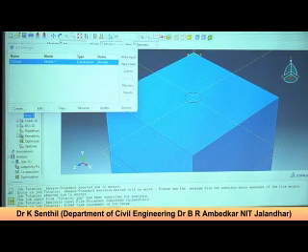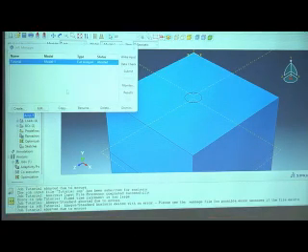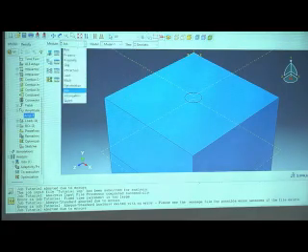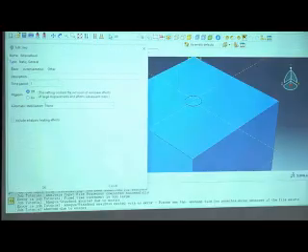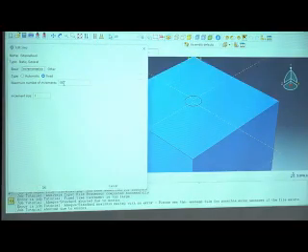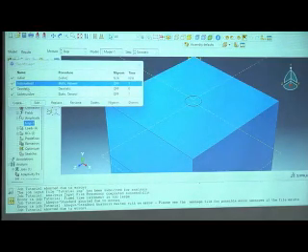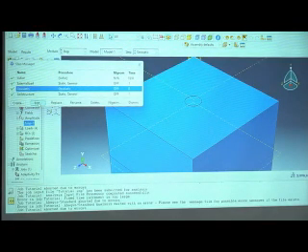Fixed time increment is too large. Go back, we'll try once more. Yes, sir. Increment size. Sir, we'll go and check the status file. Just leave the increment size at 0.0001. Is it okay, sir? Is it only one or all cases? That will take all.